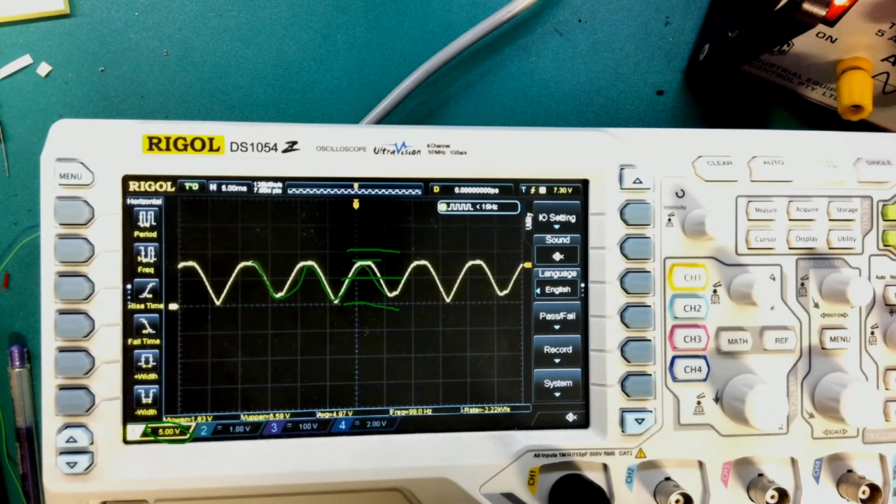And you can see up here, it's telling what the maximum voltage reading is. Down here, it's telling what the frequency of this is. It's measuring the distance between here and here and scaling it in seconds for us. Our time scale is 5 microseconds, so every scale this way is 5 microseconds. 5 microseconds, 10 microseconds, 20 microseconds.